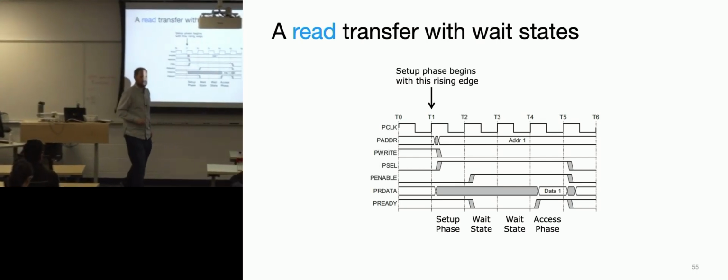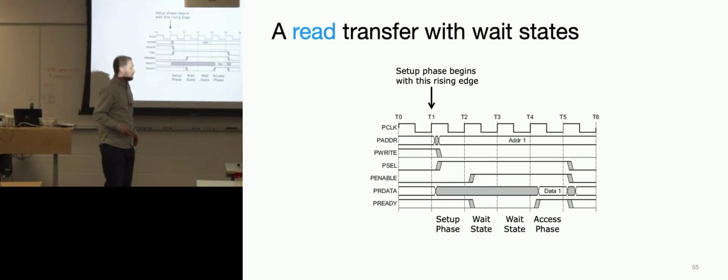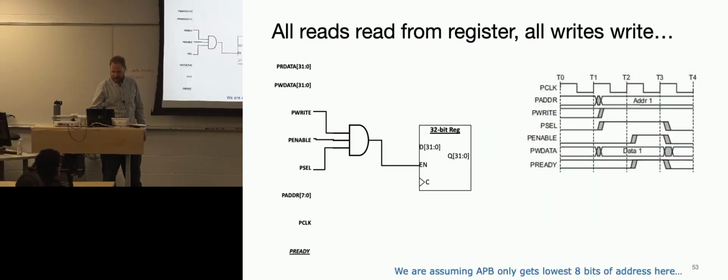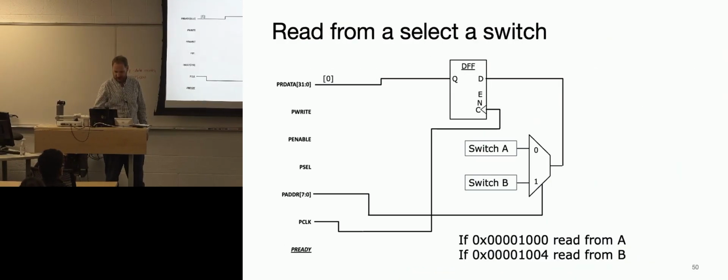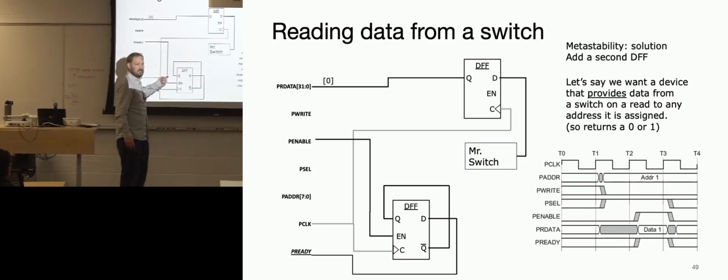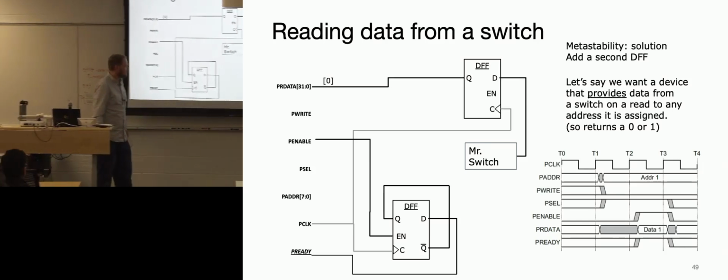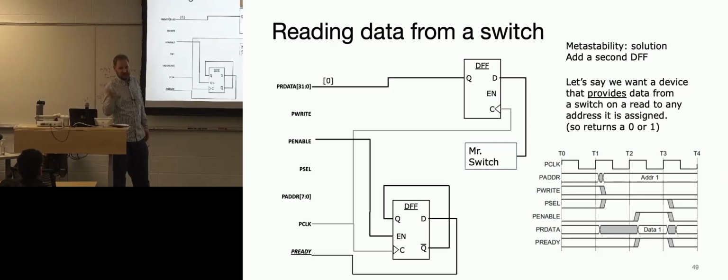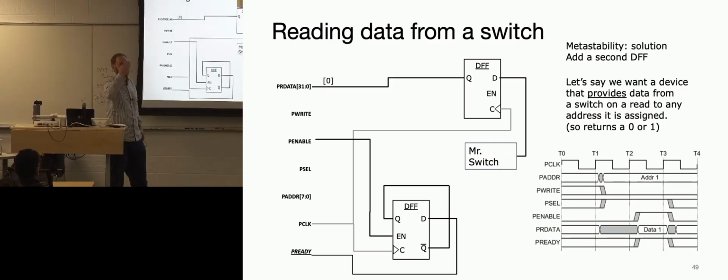What would a P-ready be wired to here? Well, it could be some circuit that I drew over here just before class. So here's the circuit that's going to cause the delay. On the exams, typically there's some external device that you're connecting to, and that thing has a data ready pin, and that would have to go through here.